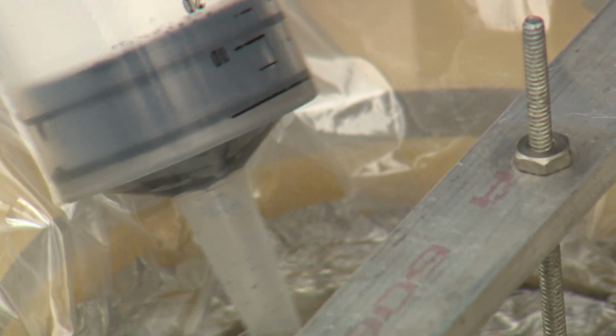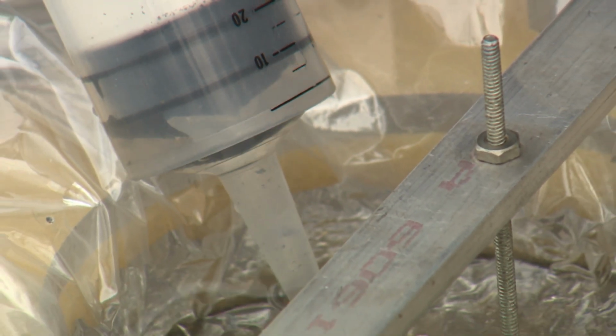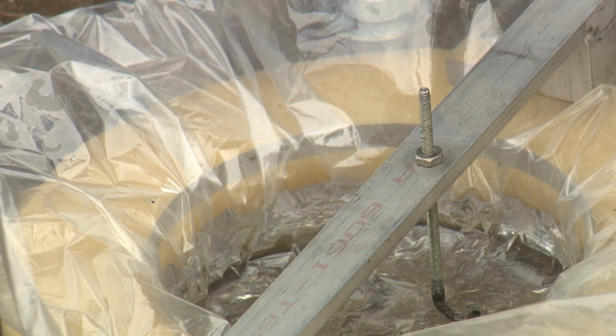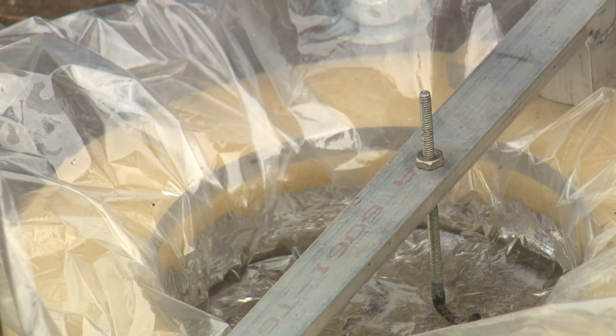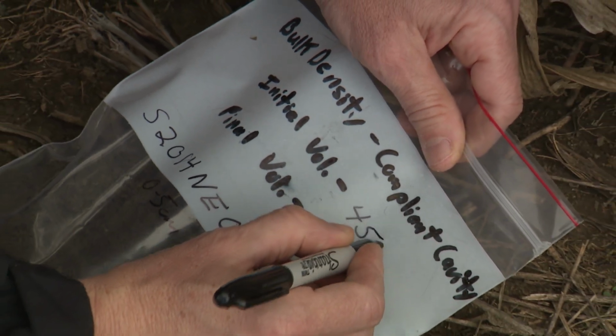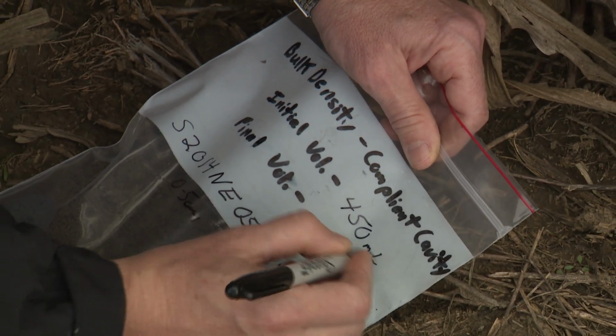And make sure there is no tenting, and the water, the plastic, everything conforms to the sides and the bottom. And if you overfill, you can use the syringe and take some in and out until the water's level is right at the tip of that hook gauge. And if you do take some out, remember to put it back in the graduated cylinder so that you can measure that.